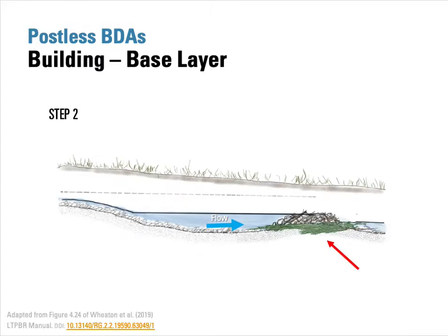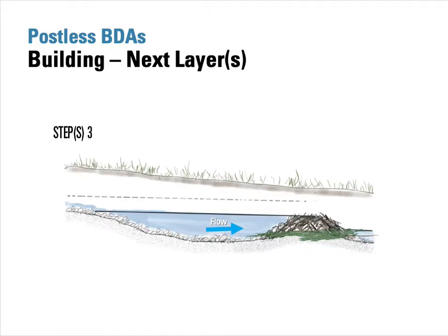You also want to source your fill material from upstream of the structure, and preferably in the pond area that you're about to build, because you're deepening the pond at the same time you're sourcing the fill. You don't want to source your fill from near the edges of the structure and potentially undermine it. You essentially then just keep adding layers in the 1/2 foot to 1 foot lifts, going slowly, and again keeping your crest elevation flat and trying to keep the base of your structure wide.